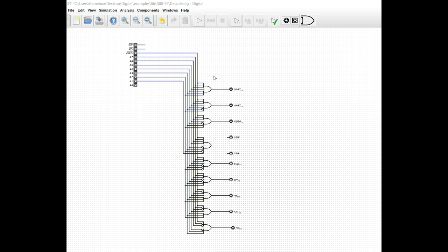That version has about 2,500 usable gates, and each macrocell of the 128 has exactly one flip-flop. So it's important to try to conserve so we can cram as much into this thing as possible. And of course we're going to talk about that here a little bit, but essentially that's what we're doing here.